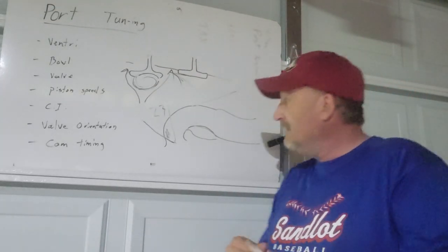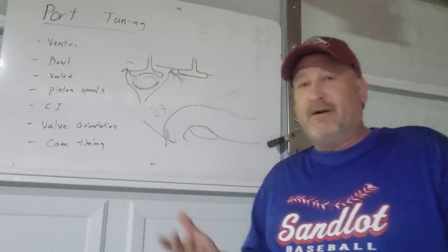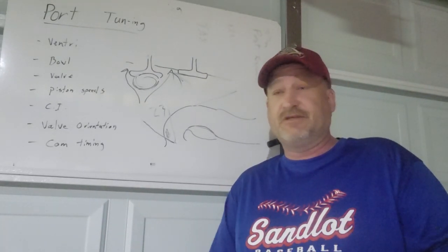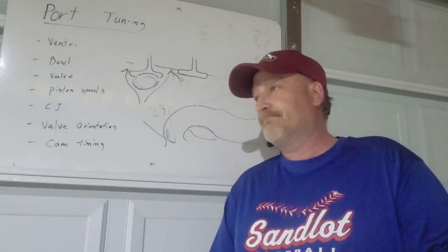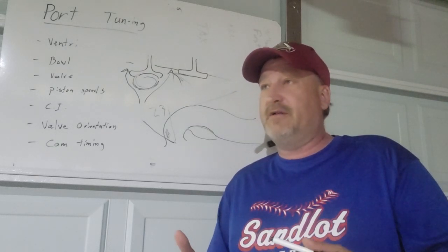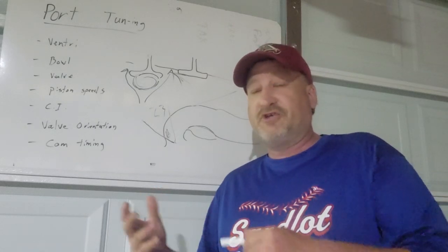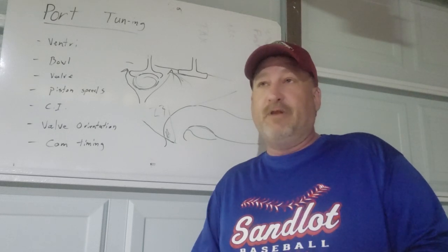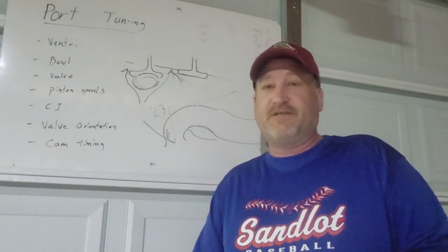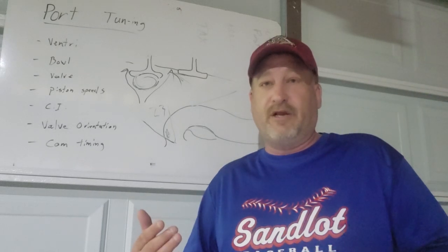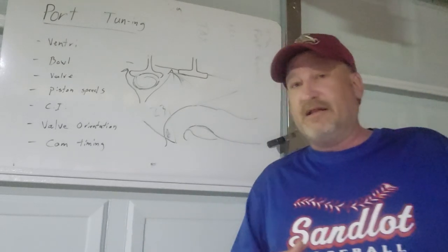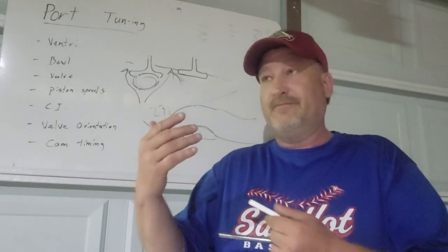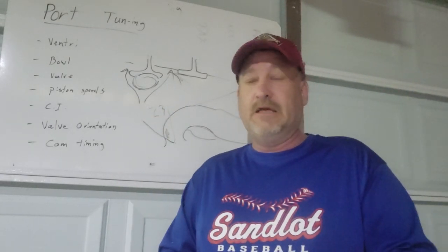Even in modern day engines, let's go back even to the late 1970s with pro stock engines or modified aftermarket cylinder heads. For Chevy, the 18 degree raised port cylinder heads, the big block, Big Dukes or Big Chief cylinder heads, they all have that raised port orientation. Even the newer LS engines have that higher port with an altered valve angle.